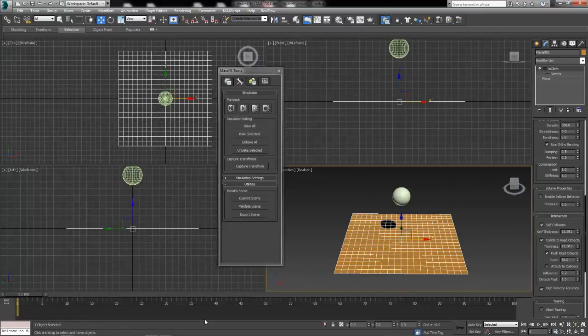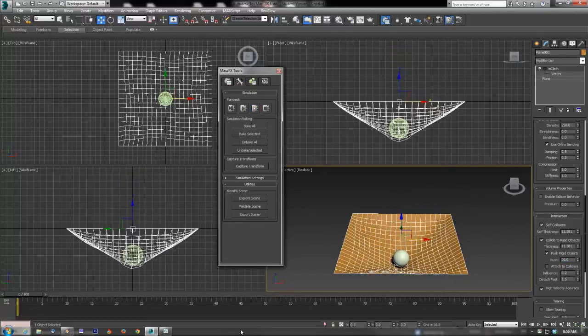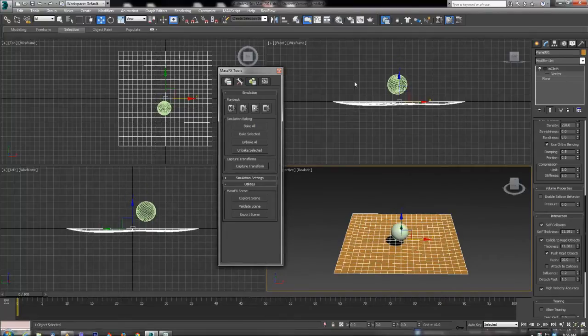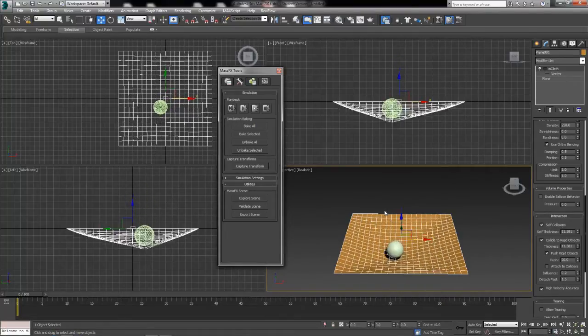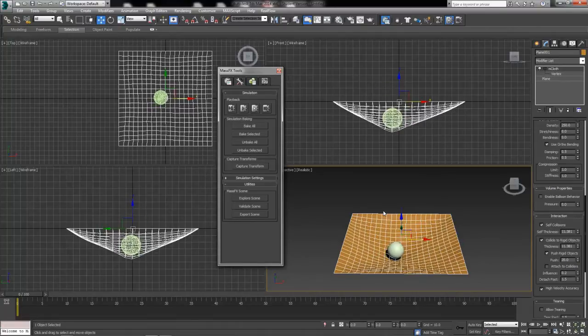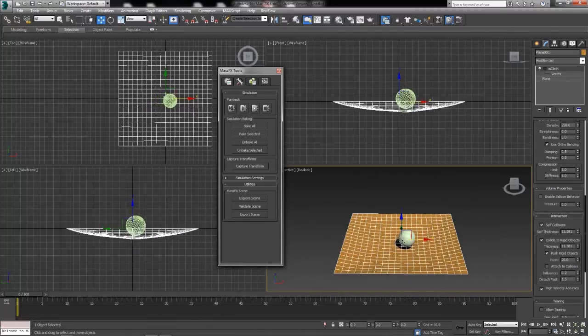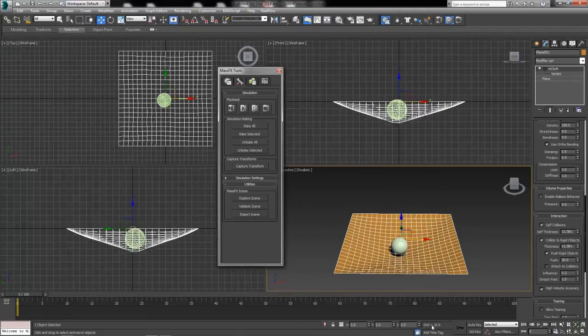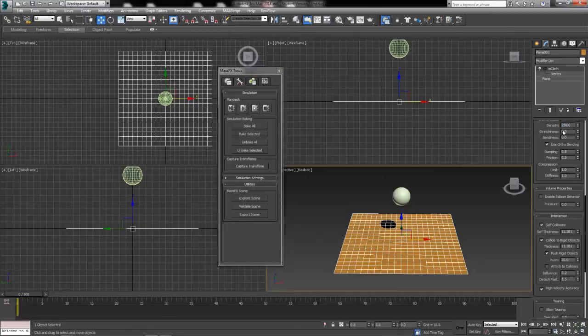So with a higher value in the push and a higher value in the density, maybe a kind of a dance in between here. Maybe we can go back to 250 density and, I don't know, 20 push, and we're going to do some experiments and see exactly the different amounts of deformation, shape changes, and other things that can keep this rigid body set up on here. So see, now our times 100 or whatever it was, 250 is working pretty well. And you'll want to try and get these to work, however best you want the cloth to react.